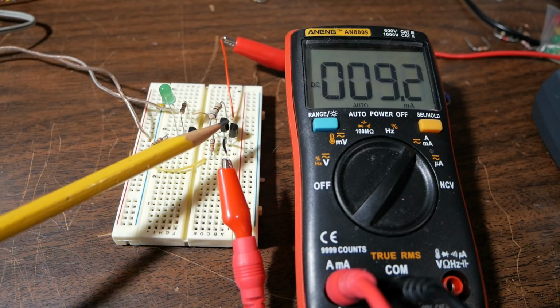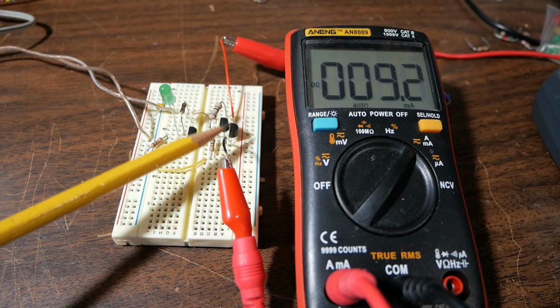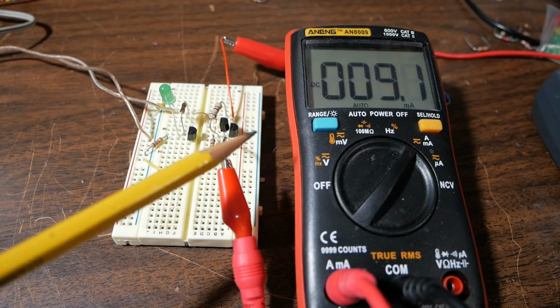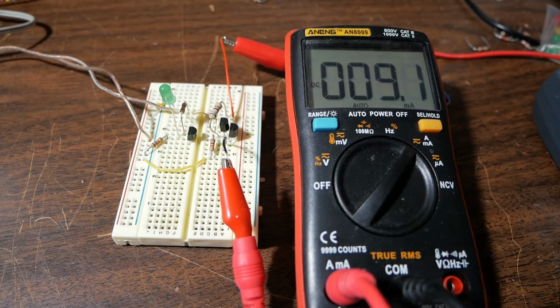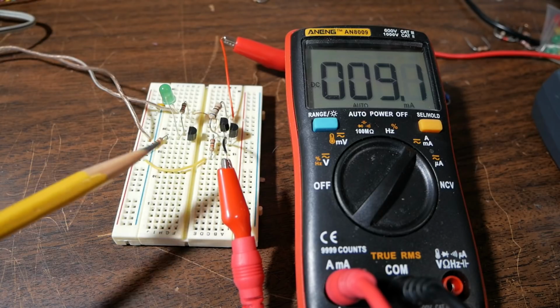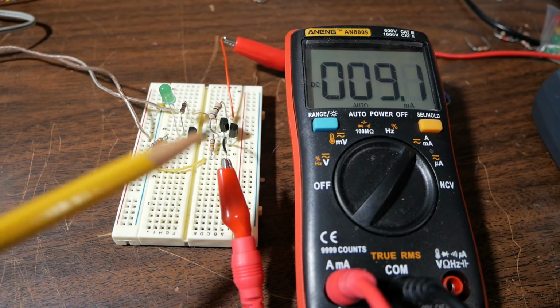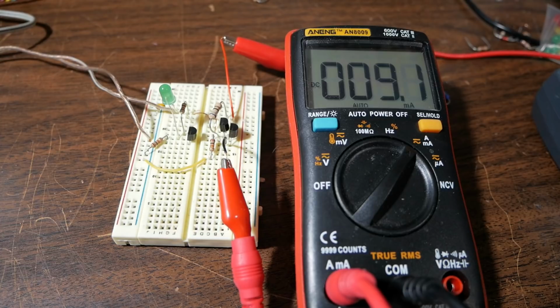And in a way that's expected. I mean, it's supposed to be a better performing circuit having 2 active devices, provided it doesn't break out in oscillations and stuff in use in the circuit. Okay, so the next test, I'll hook up the function generator, the oscilloscope, and we'll do some dynamic tests and see how it performs by putting a square wave across it.